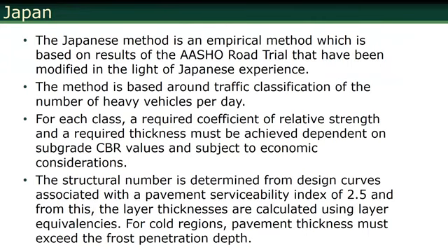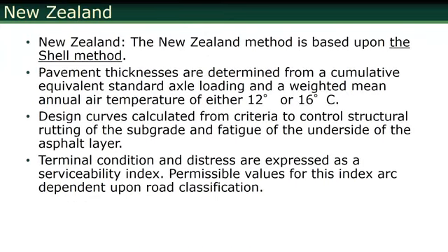Japanese method is an empirical method based on the AASHO road test. They just use the AASHTO 93 design slightly modified for their conditions. So I'm not going to read all this, more for reference purposes for you. New Zealand is also the Shell method. Again, I'll talk about the Shell method, very similar to the mechanistic empirical pavement design guide.